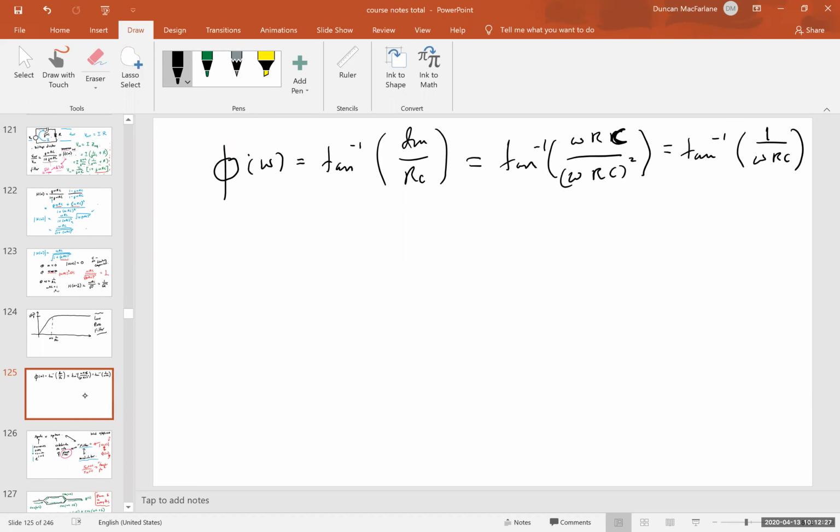And again, we know that the inverse tangent is a transcendental function. It has a Fourier series that has every single power, linear, quadratic, cubic, and so on. And if I'm adding all those together, I have to have a dimensionless number. Once again, I see the role of RC and omega as the dimensionless number, as omega being inversely proportional to RC, and RC having units of time, and frequency having units of 1 over time.